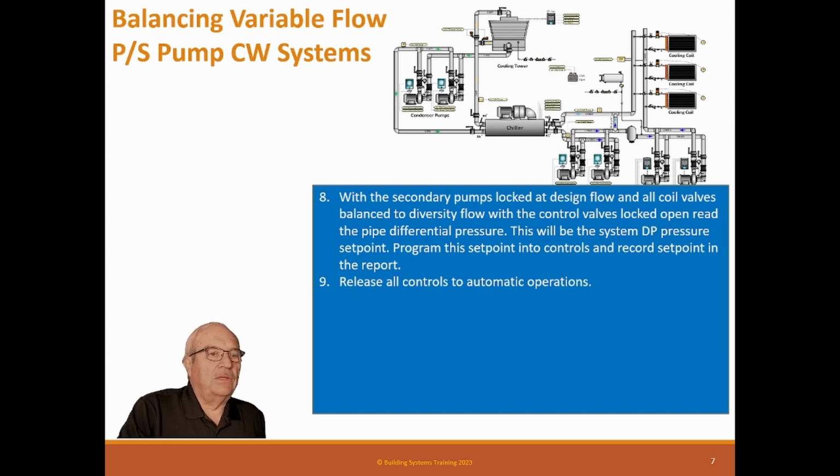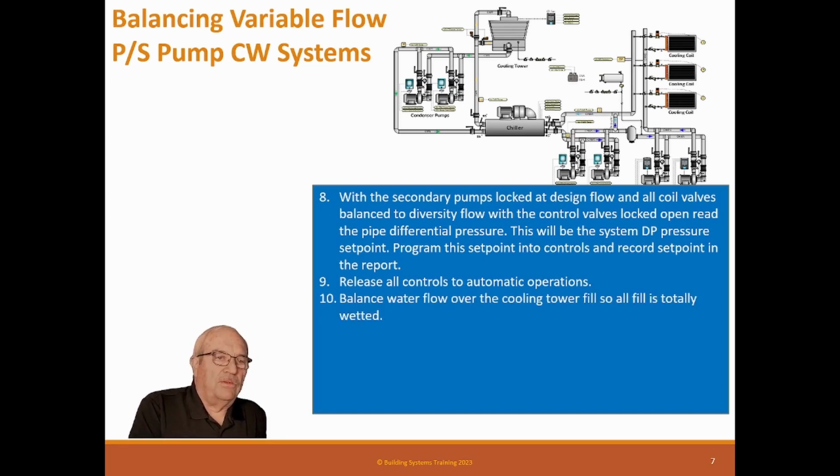Okay, so release all controls to automatic operation. Please don't forget to do that. It's a little embarrassing when you forget to do that. Balance water flow over the cooling tower fill. Yeah, so it is all totally